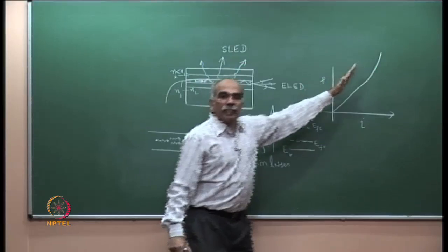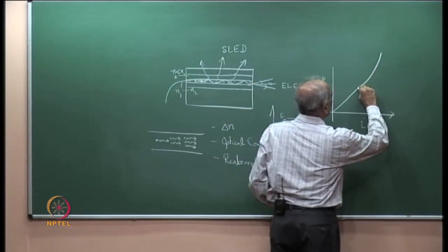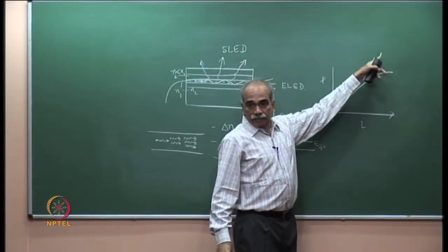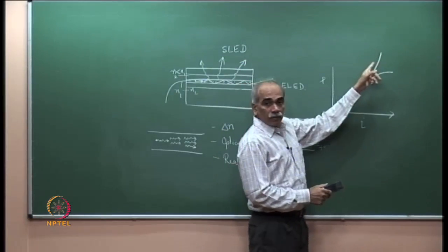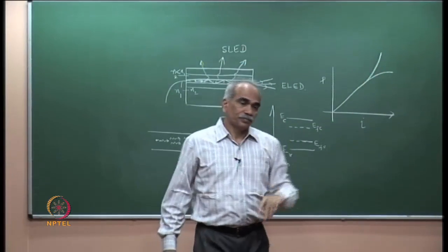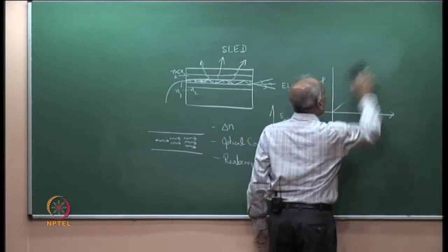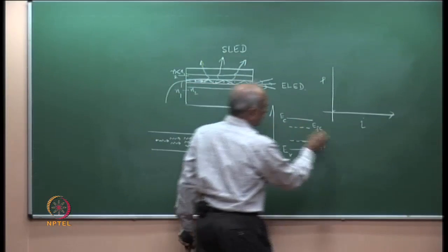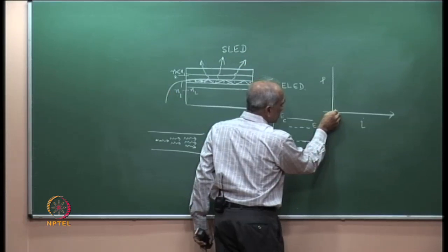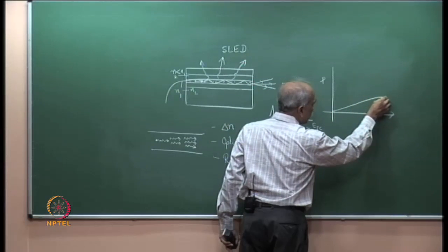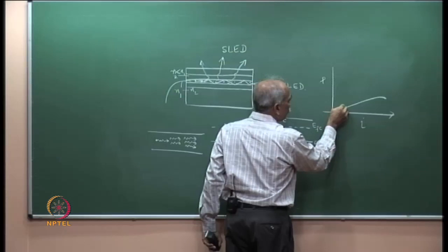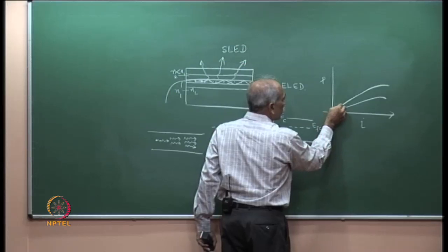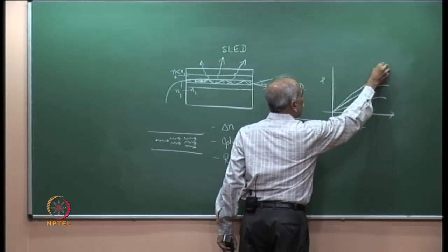However, even in an edge emitting LED, normally you will see saturation doing this. Normally, you would not see this, but you will see this if you go to low temperatures. If you reduce the temperature, you will indeed see a graph like that. So what I am now plotting are the temperature dependent output characteristics of a superluminescent diode. These are experimental curves reported in the literature.